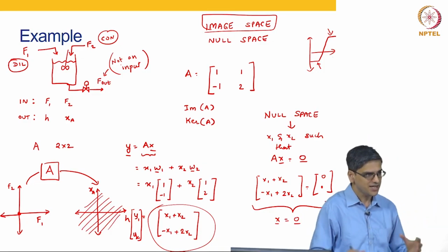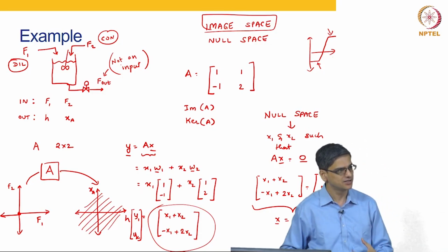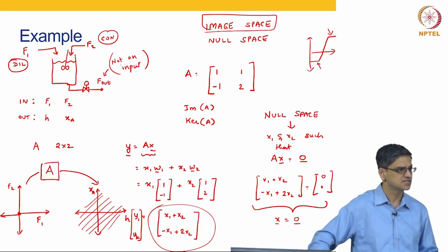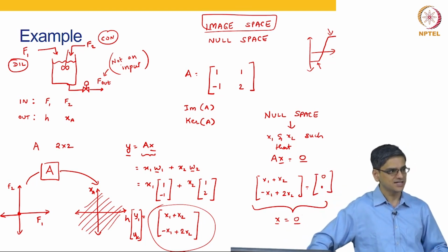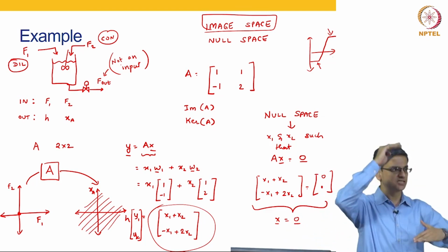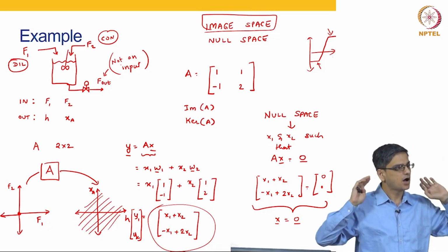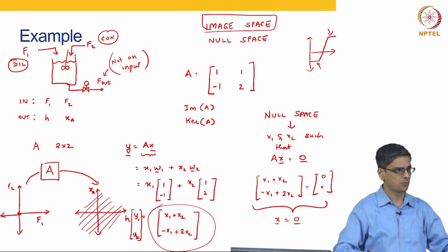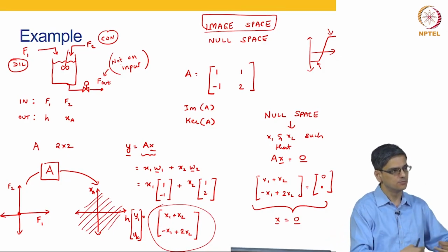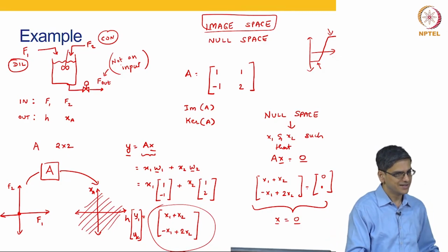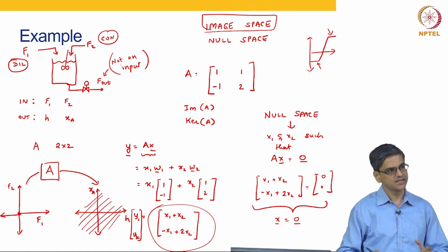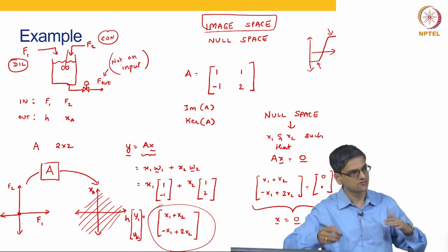So, how do you handle this situation in a physical situation? By implementing constraints, by saying that between minus 0.5 and plus 0.5 I am linear, and I am not allowed to go beyond 0.5 or below minus 0.5. In reality you wouldn't even give yourself so much leeway.